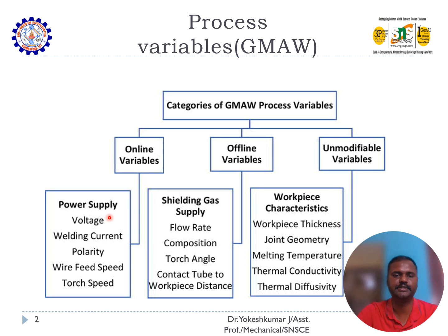By controlling the voltage and current, we can control the heat developed in the welding process. By controlling the heat, we can control the microstructural changes, and by controlling the microstructure, we can control the mechanical properties. The second case is the polarity. In the previous video we discussed direct polarity and reverse polarity, which is useful for joining thin and thick metals. And for wire feed speed, the amount of deposition of the consumable electrode depends upon the wire speed and the torch speed also.